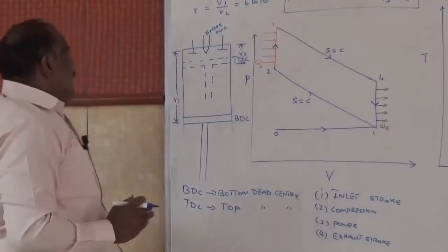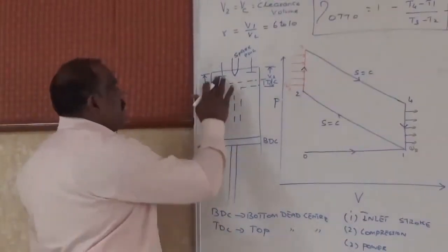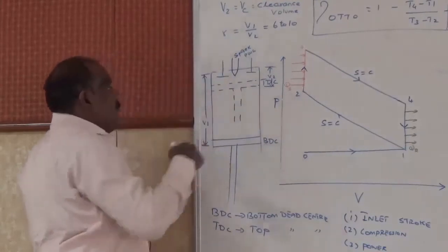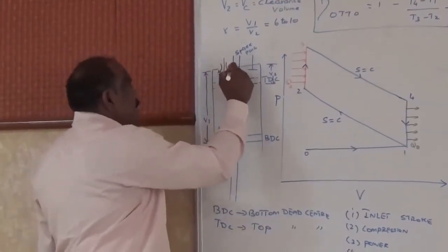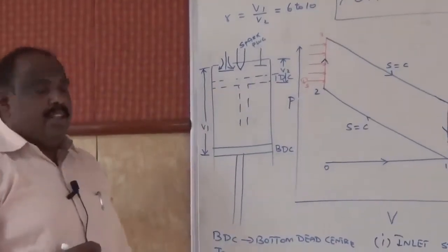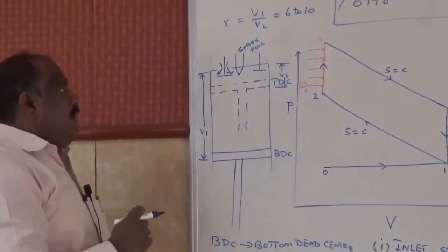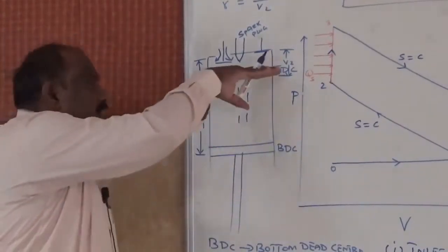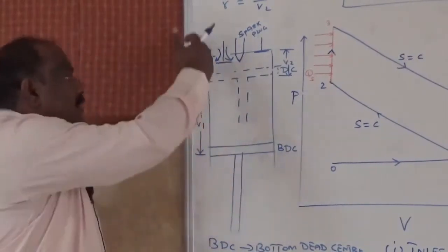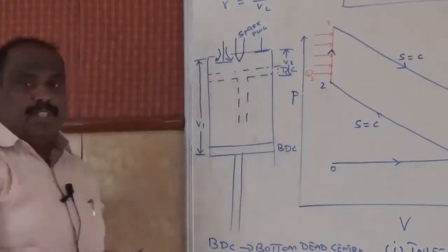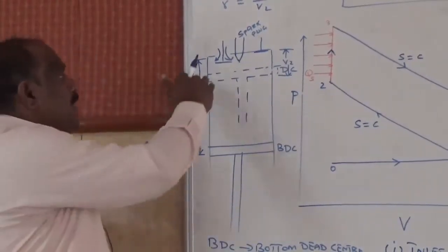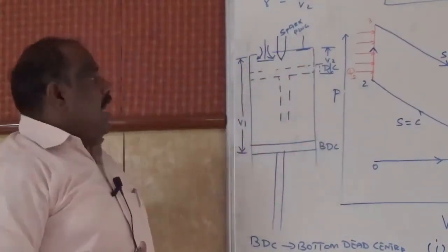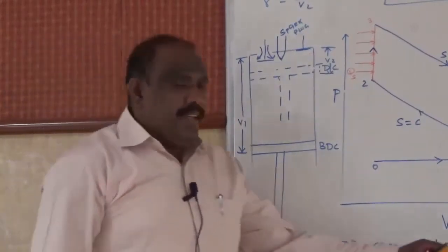And in case of the petrol engine, during the suction stroke or the inlet stroke, the inlet valve remains open. So when we are going to make this valve push down, there will be a clearance so that the petrol and the air from the carburetor after enough mixing will be entering the combustion chamber through the inlet valve. During this stroke, the exhaust valve remains closed. The piston will try to move from the TDC to BDC, creating more vacuum, and hence there is a flow of petrol and air mixture into the combustion chamber. So in the suction stroke or the inlet stroke, the petrol and the air mixture enters into the combustion chamber via the inlet valve. The piston moves from the TDC to the BDC, and the exhaust valve remains closed. This completes the inlet stroke.